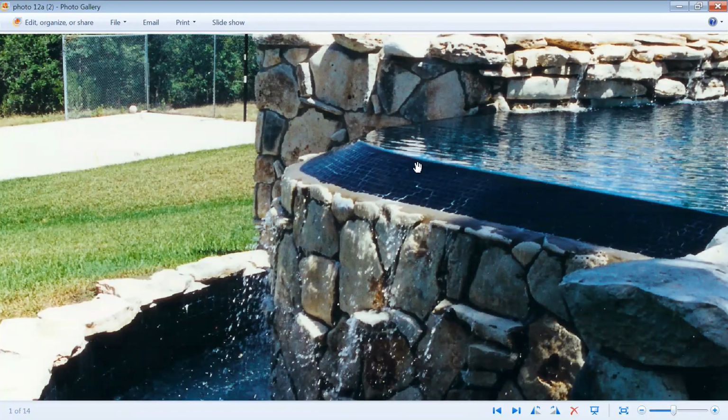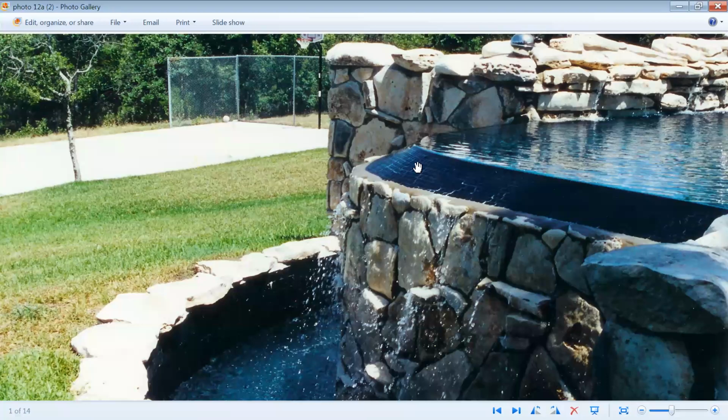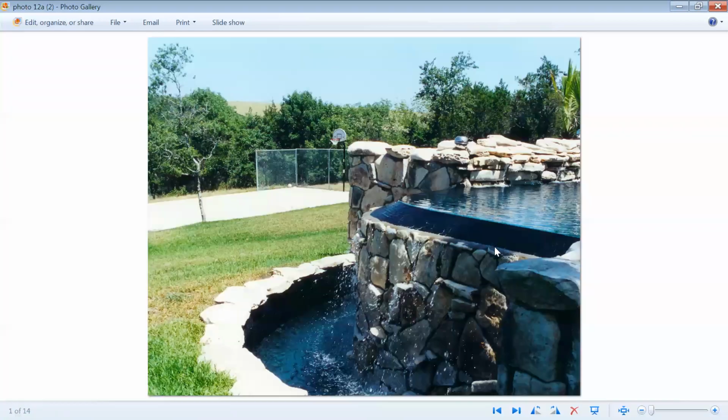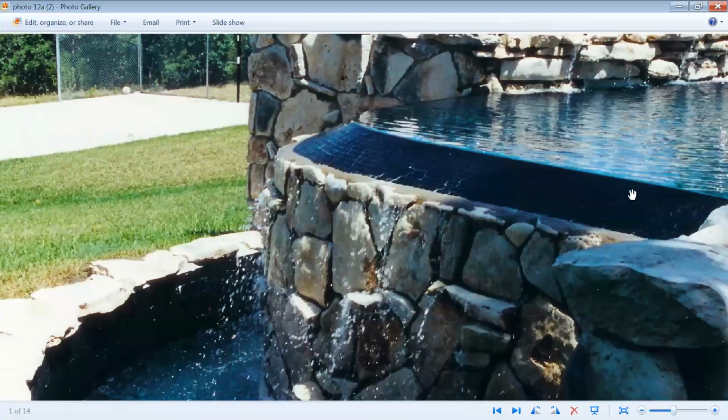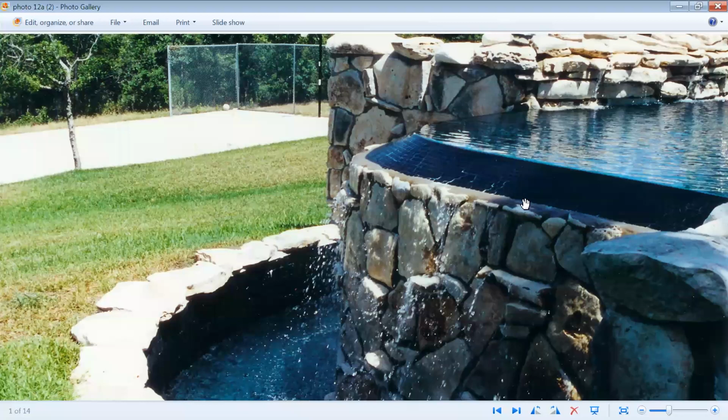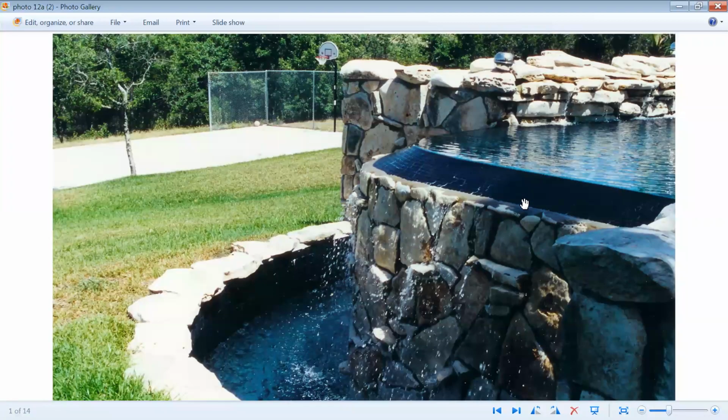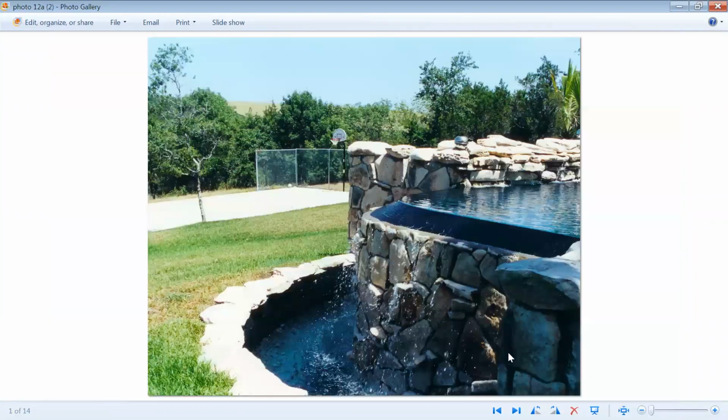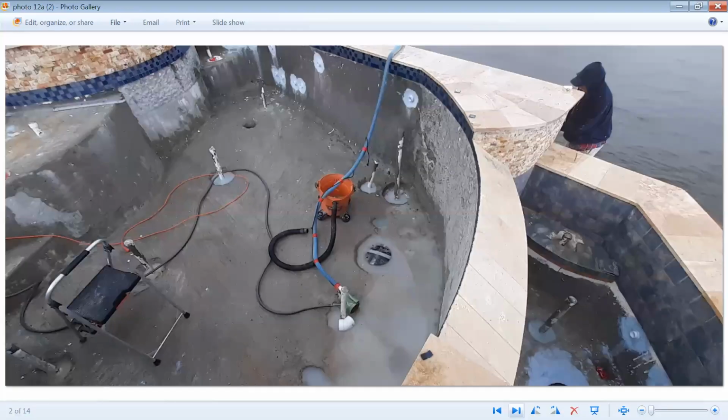And this is very difficult because the homeowner ends up paying higher energy costs. There's much more evaporation. There is a lot more chemical loss as well. So not salt, because salt stays in the water, but a lot of chlorine, loss of chemicals. And compensating for a really poor negative edge, for example, with the level, by just running more water over the edge is a very poor substitute to making sure that the edge is level and starts off fairly close to level in the beginning.